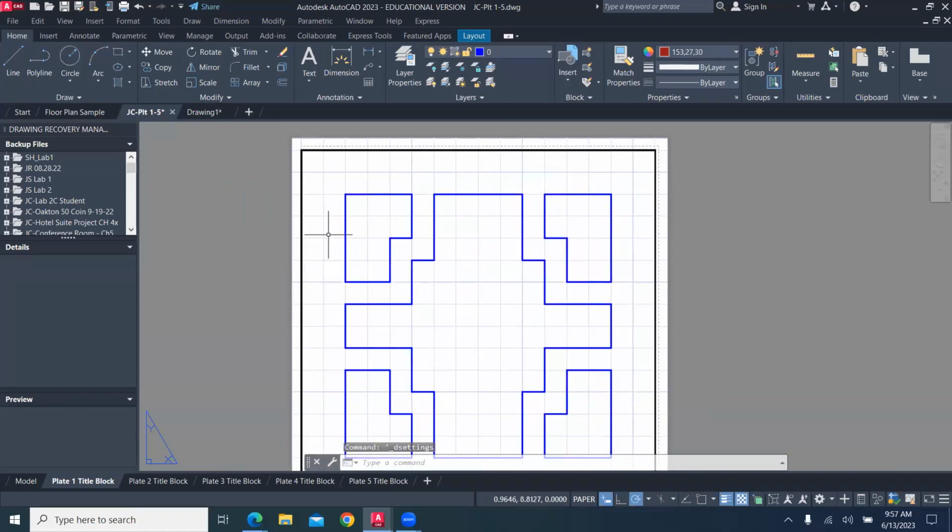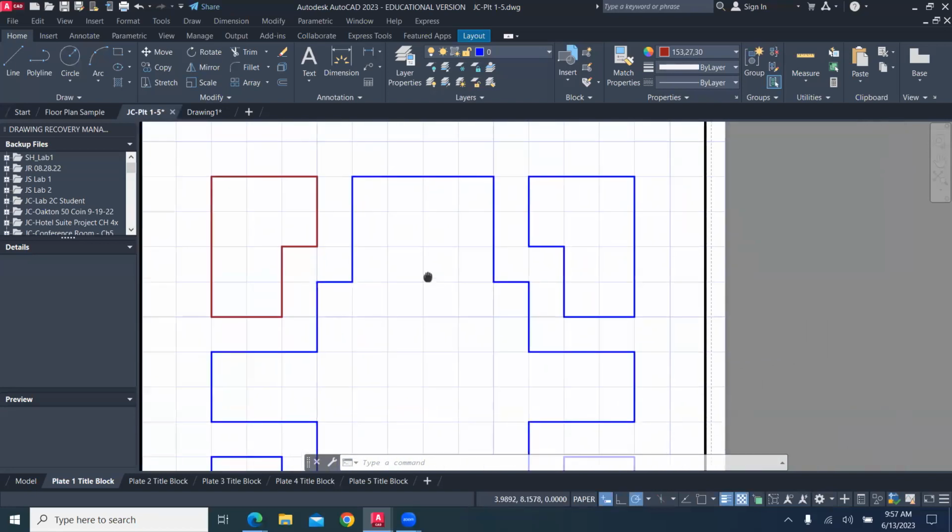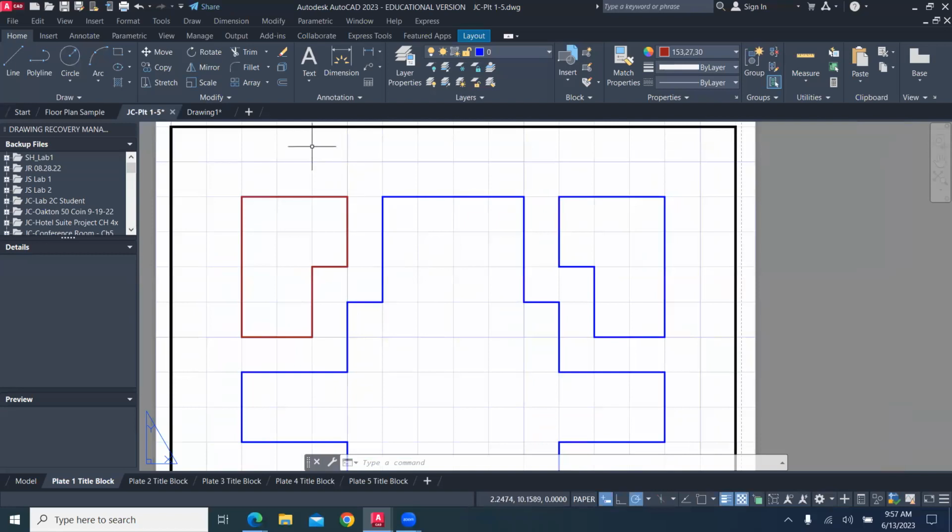If I have the drawing set up like that, and I just change my color, I just come in here with the line command. And as I draw, we'll just use the grid. And then I'll hit escape, pick up the pencil. If I turn the wheel on the mouse, or push the wheel on the mouse, I can get zooming and panning enabled through the mouse.